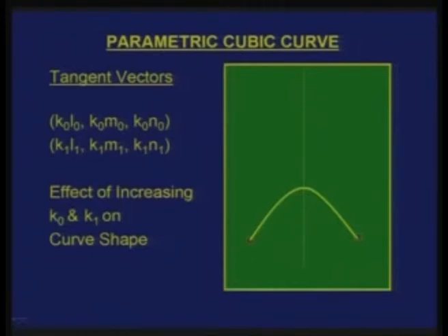The curve moves. If I look at the tangent, it has the same direction as the previous one, but the curve is different, because it is non-unique for given direction cosines. If I increase further, it also starts forming loops, which is an undesirable characteristic as far as curve definitions are concerned.